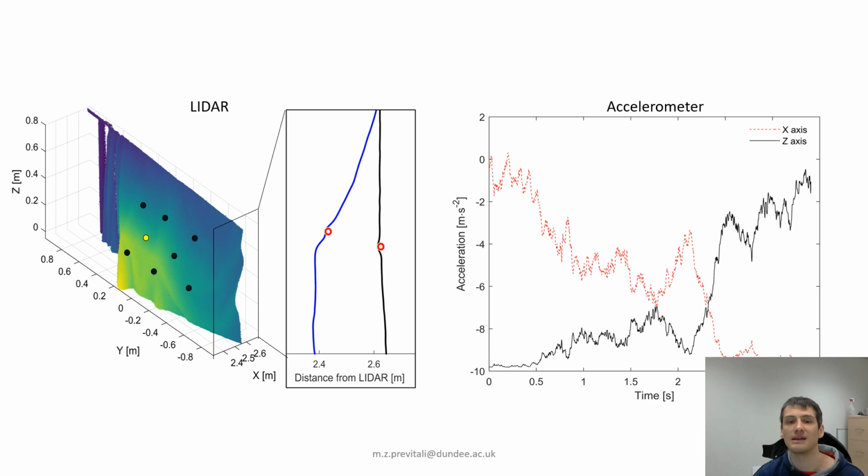In red you can see the target and the inertial measurement unit, which recorded data that was not usable per se to obtain the displacement, because it was a very long test, and therefore the noise tends to sum and produce unusable data. But you can see here the change in the gravity vector, which confirmed that the entity of the displacement measured with the inertial sensor were the same as with image analysis and with LiDAR.